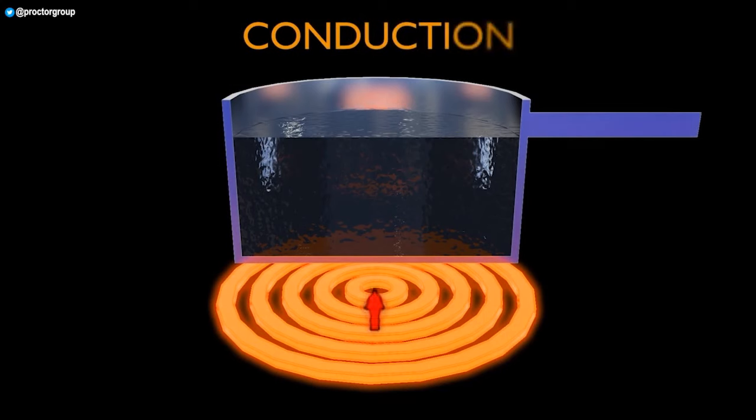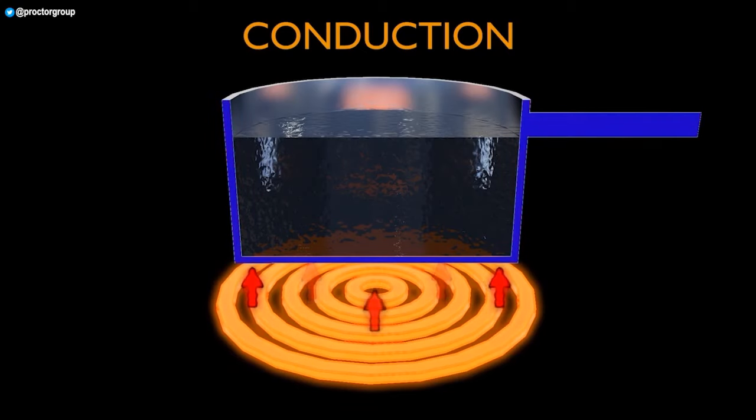Conduction. Conduction happens where two objects are in contact with each other, like the base of the pan sitting on the hot plate. This direct contact lets the heat flow from the warmer hot plate to the colder pan, either until the temperatures equalise or the pan is removed. Most building insulation boards, such as mineral fibre, polyurethane, for example, work to resist heat transfer by conduction.